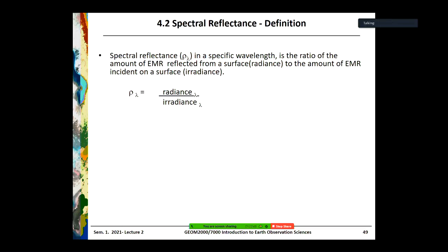So from that light coming down, it's illuminating the target. Now, not all of it is reflected away. Some of it's absorbed, but because the lino on the table is different to the plastic on the monitor top, the amount of reflected light is different. So it's much lower here.